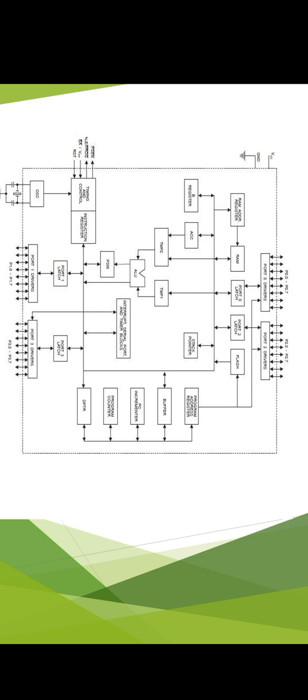Then SI is the serial interface device. It contains RXD and TXD in port 3, that is in serial communication mode. T0 and T1 are timer 0 and timer 1, timing devices in the 8051 family using 4 registers, that is TH1, TH0, TL1 and TL0. Then ROM, read-only memory, has masked ROM, EPROM or flash EEPROM. 4 kilobytes are available